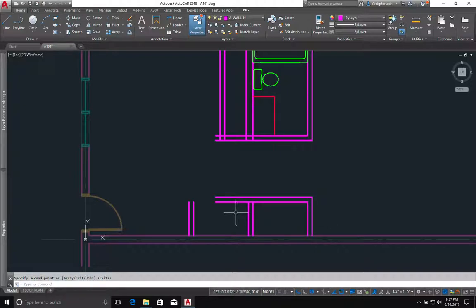Those of you who want to know how to view distances, how to measure distances, you can come up here to measure, use the whole drop down and say I want a distance, and I want my distance clear on the inside of this, and you can see that says 5 feet. And do I want to do it again? Yeah, I'll do it again. I'll go from here across and up, and that's 5 feet, and I'm down now, so I can come down and click exit.